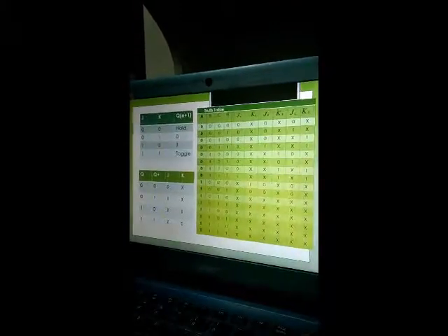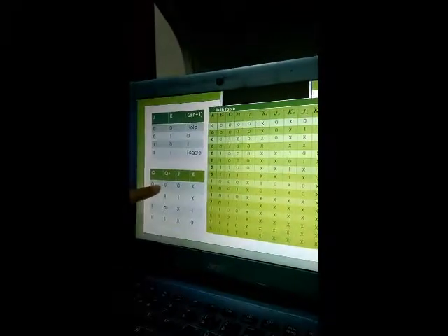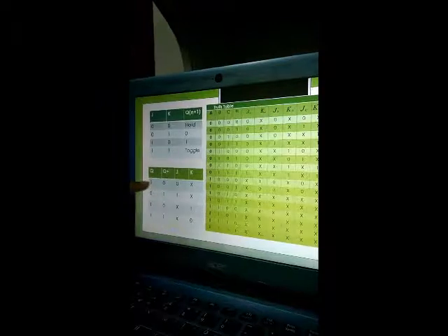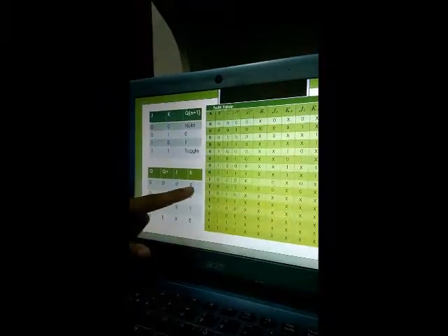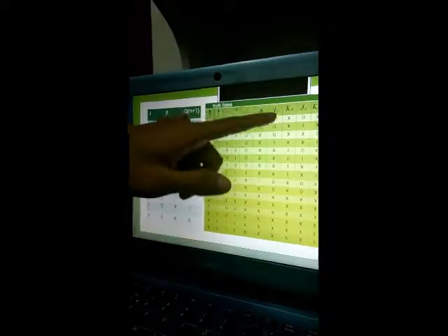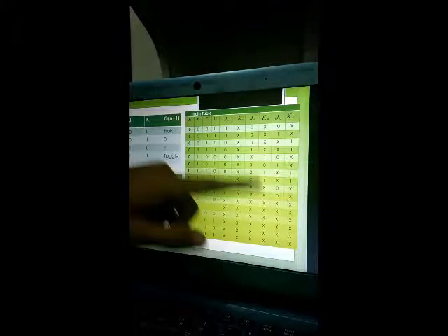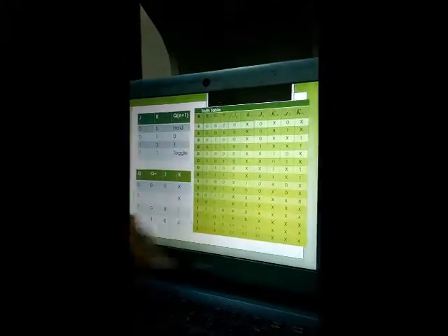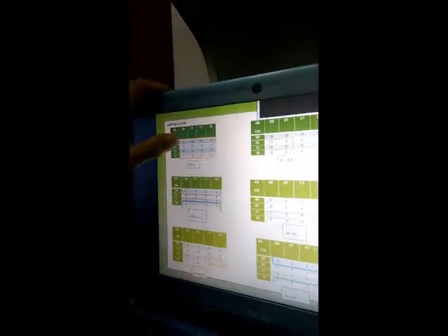From the truth table here, we get for 0 0, when the current state is 0 and the next state is 0, the output of JK will be 0 and don't care, and we put the outputs in the table, so we can create the Karnaugh map from this truth table. Here is the Karnaugh map for the J and K inputs.